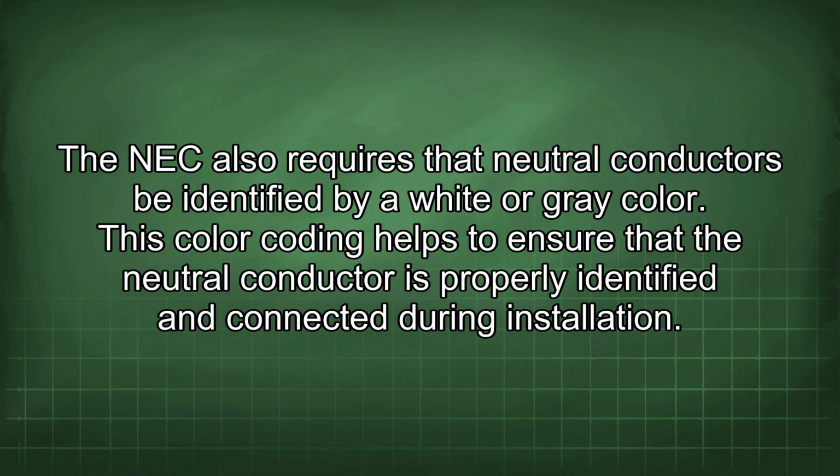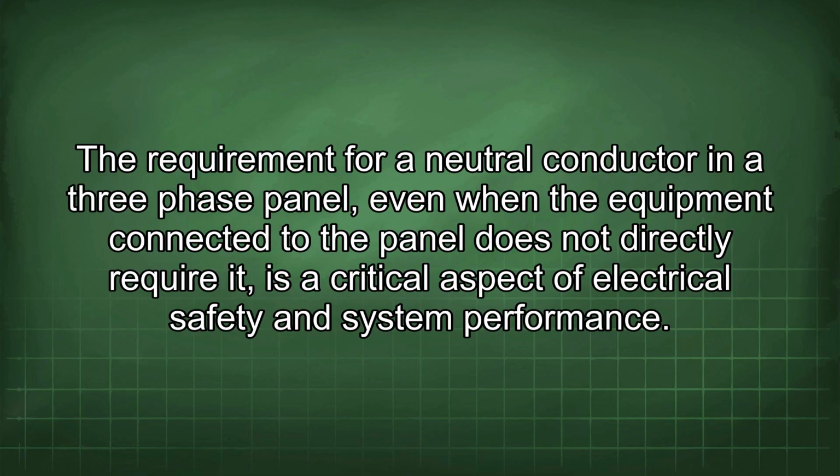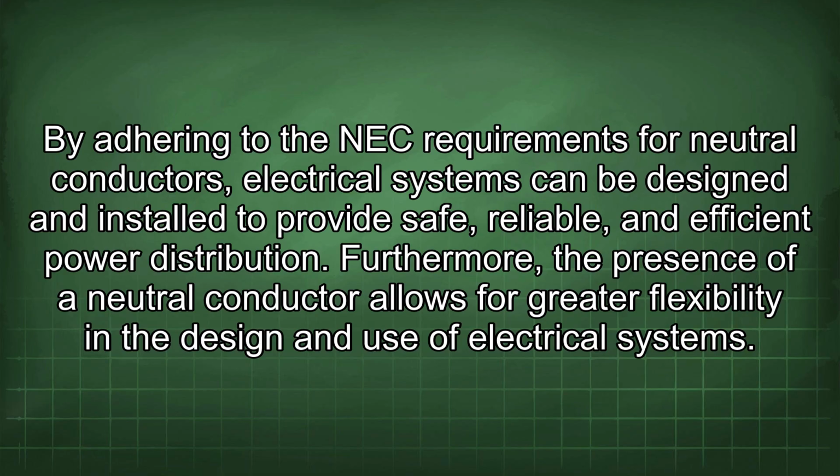The NEC also requires that neutral conductors be identified by a white or grey color. This color coding helps to ensure that the neutral conductor is properly identified and connected during installation. The requirement for a neutral conductor in a three-phase panel, even when the equipment connected to the panel does not directly require it, is a critical aspect of electrical safety and system performance. By adhering to the NEC requirements for neutral conductors, electrical systems can be designed and installed to provide safe, reliable,